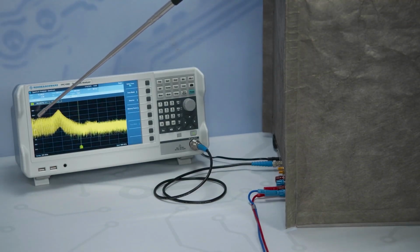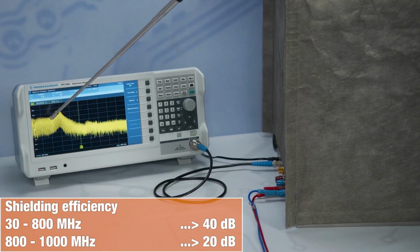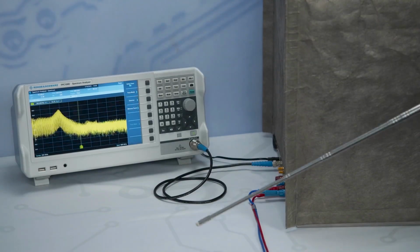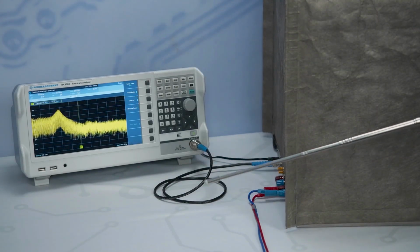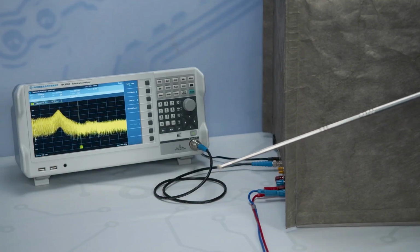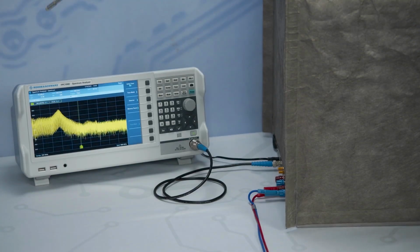You see now here the result of the measurement, and what you can see here is the switching frequency of an internal DC-DC converter. And this resonance here at 150 megahertz comes from the internal resonance of the setup, because of the distance of the device under test to the reference plane and the inductance of the power supply cables to the RF current transformer. Exactly this creates this resonance frequency here.